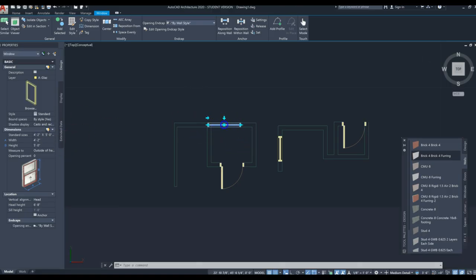So, you know, maybe you go back and you click again and you see how close you can get, and you say, well, hang on. Wait, you see that white box? I need to move it 4 inches to the side, and it's currently moving at 1 foot 10 inches to the side. So I do 4 inches, I hit enter, and hey, it just moved 4 inches. And from here, I could use the nudge tool. I hold Control, and I hit the right arrow, and I hold the right arrow down perhaps to keep nudging multiple times. Or you just click in the middle, you start to move it to the side, and then you type in a smaller amount of movement you want, 3 inches, hit enter on the keyboard, and there it is. And from here, I can definitely nudge it over using Control and right arrow.